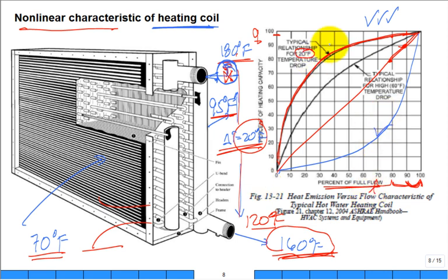So they kind of come in here with a very rapid knockoff, such that if you combine this nonlinearity with that nonlinearity, the percent turn on the valve would result in a net percent reduction in the Q transferred in that heat exchanger in a one-to-one relationship. It would be more straight, easier to control, less sensitivity. It would be equal sensitivity throughout the range of the valve positioning. So that's how they solved this problem.